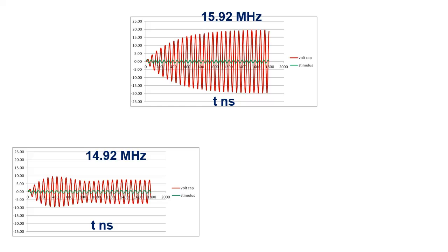Next we use 15.92 MHz as the frequency of the stimulus. Here the steady-state amplitude across the capacitor is even larger, around 20 volts.